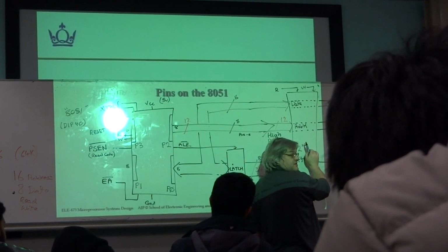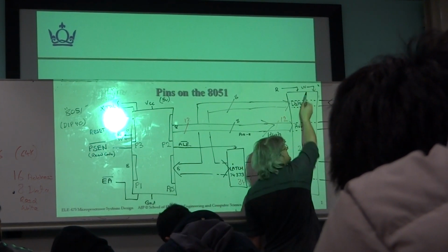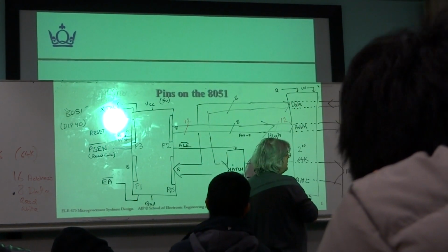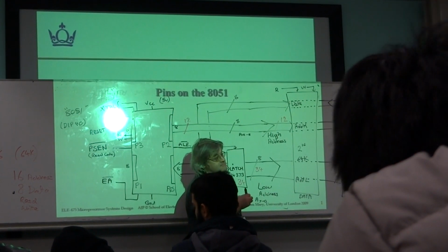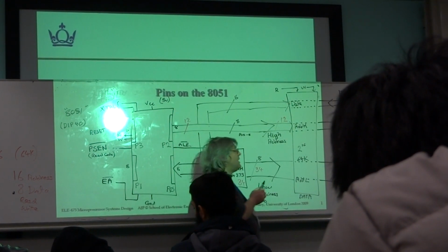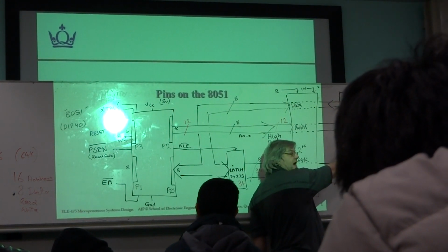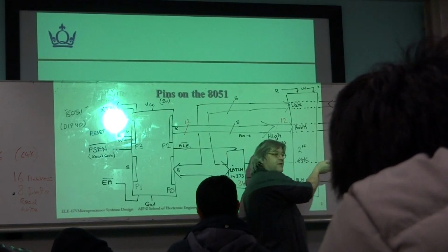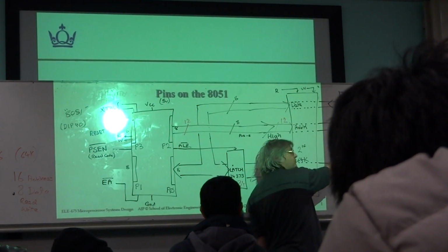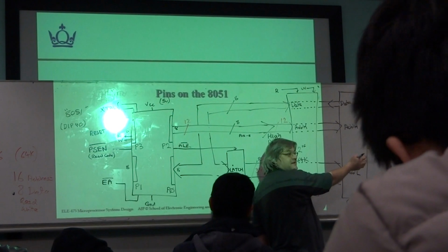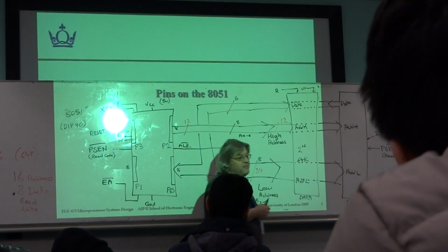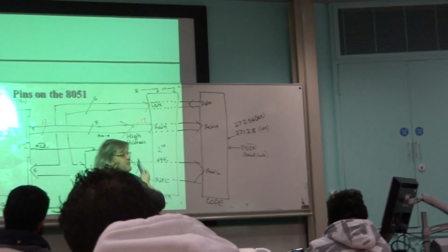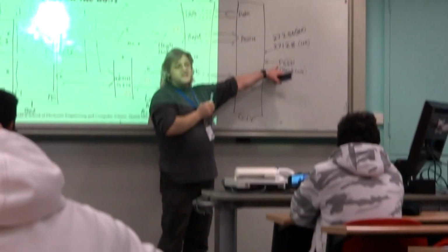This is data memory. The assumption is you're going to be able to write to this as well. You have a special signal to write to it if you want to write to it. Okay, but the ICs are the same, like the numbers are the same, right? What do you mean by the numbers? Like we could use it for ROM or for RAM. It's up to you as the designer how you're using the IC. So this could be a RAM, and this could be a RAM if you want to. That's up to you. The microcontroller doesn't know that. But even if this was a RAM, the microcontroller has no way to write to it because it has no control signal for writing to what it thinks is code memory. But for data memory, it has a separate read signal and a separate write signal. For code memory, there is only a read signal.